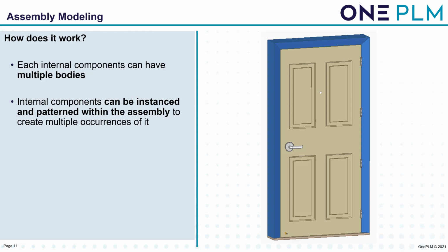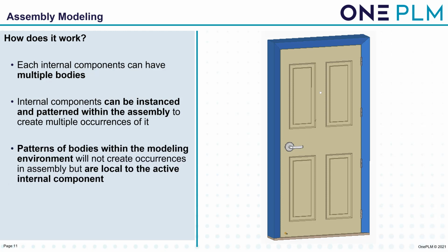Internal components can be instanced and patterned within the assembly to create multiple occurrences of it. Patterns of bodies within the modeling environment will not create occurrences in assembly, but are local to the active internal component itself.